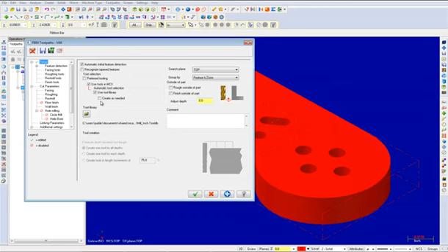Tool selection tells Mastercam where to locate tools for the FBM generated toolpaths. Preferred tooling searches the preferred tool list defined in the facing tools, roughing tools, rest mill tools, and finish tools pages to find an appropriate tool for the operation. Mastercam searches the preferred tool list from the largest to the smallest tool and stops at the first tool small enough to machine the feature.